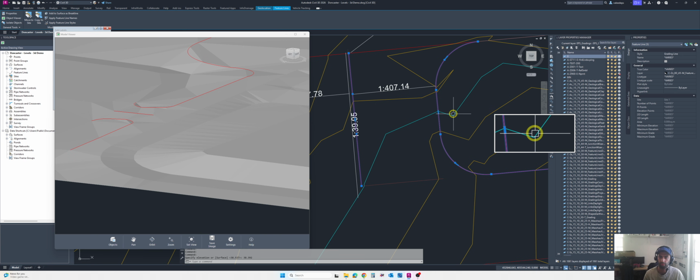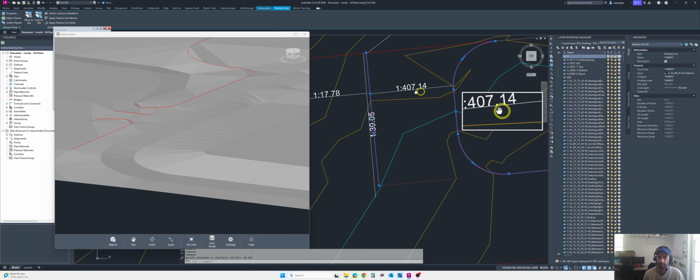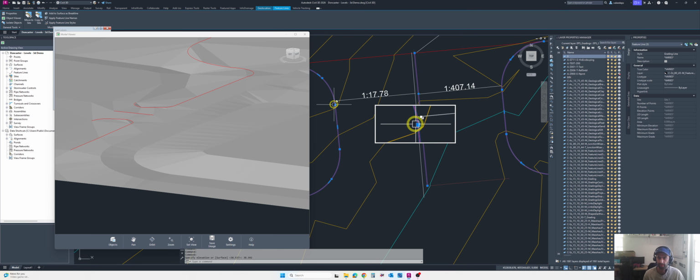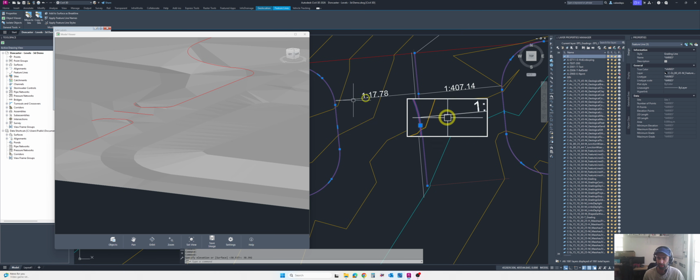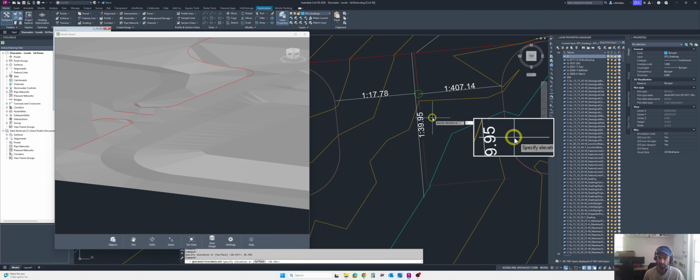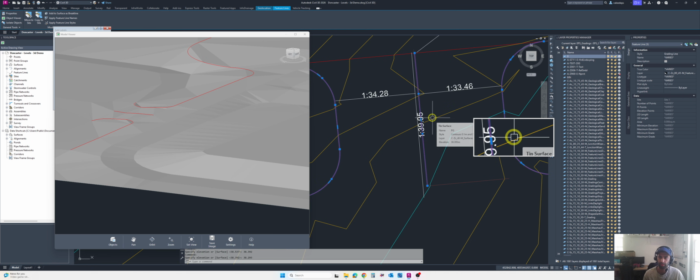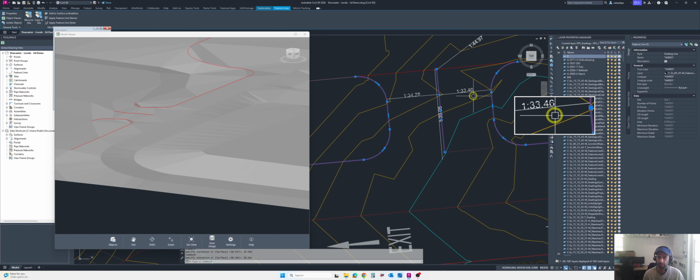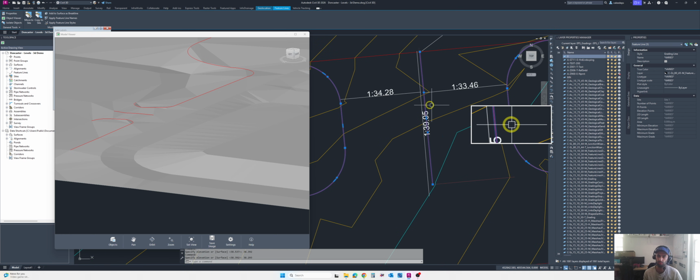38.392 is a bit flat now, and then we can lower. This one is 38.193, so it goes higher to 38.293. So it is 1 in 34 and then 1 in 33. So now we are getting there. I want it at 1 in 40.